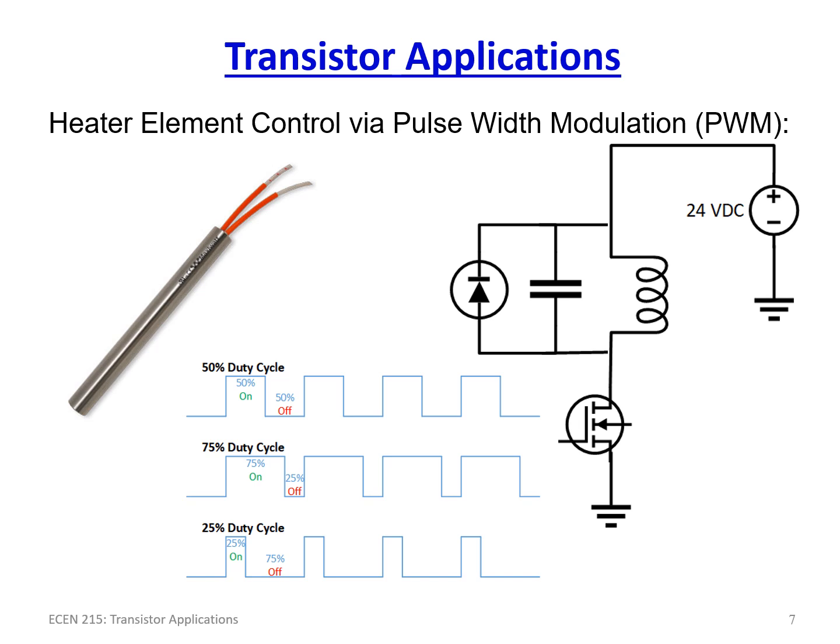You provide the frequency or the period of the signal, and a duty cycle to the register, 0 to 100% or some fraction thereof, and you can get very fine control of the elements in question.